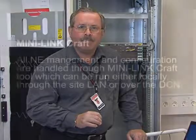Make sure that the local craft terminal software is correctly set up and that the Minilink Service Manager software is installed on the computer if it is required. Later versions may be configured via the USB port using a normal web browser.